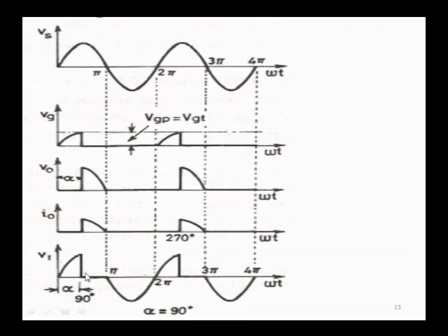But while explaining, this is enough. In the examination, if you are asked to explain the R firing circuit, you can stick to only these two voltage levels to explain this resistance firing circuit. So, when the gate peak voltage is equal to the gate trigger voltage, your SCR will turn on exactly at 90 degrees.